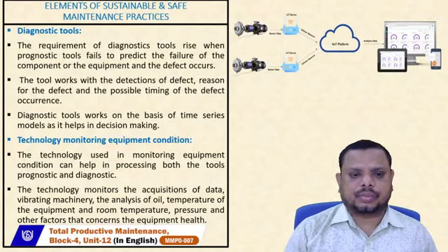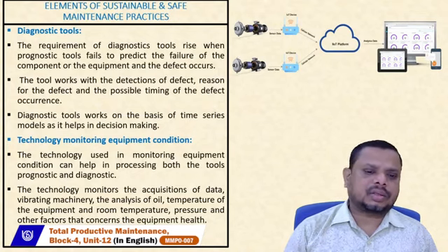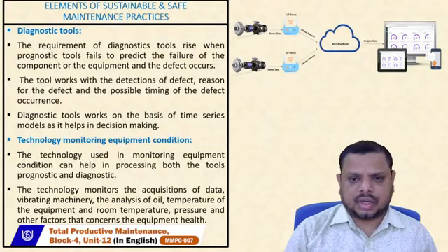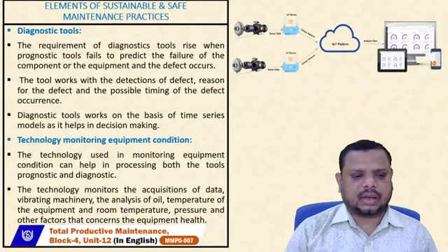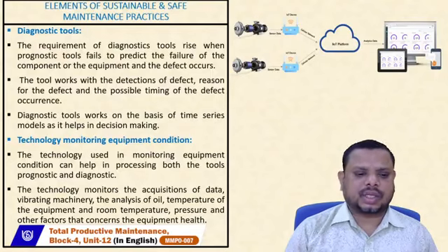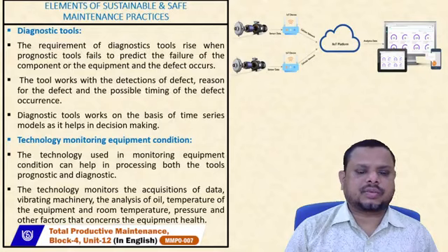If you switch on the motor and run it for a large amount of time, which is known as run time, in that case you have to take monitoring factors. The first one is temperature of the equipment, which must be checked. The next important part is you have to check the bearing conditions, whether the chances of wear and tear should occur.